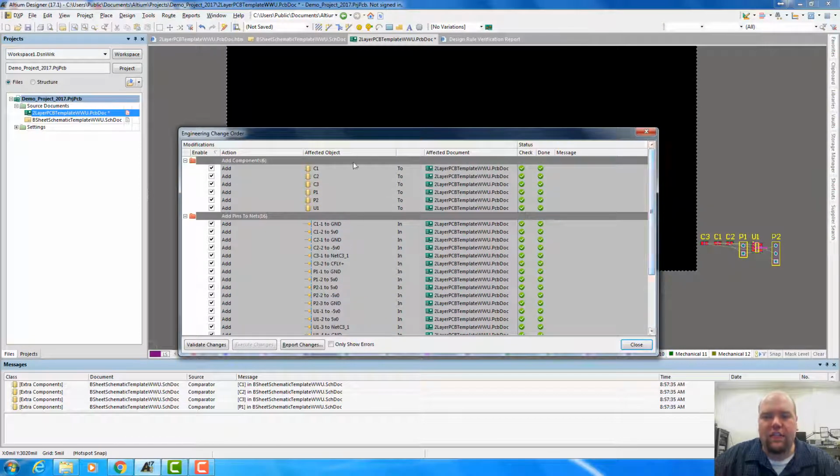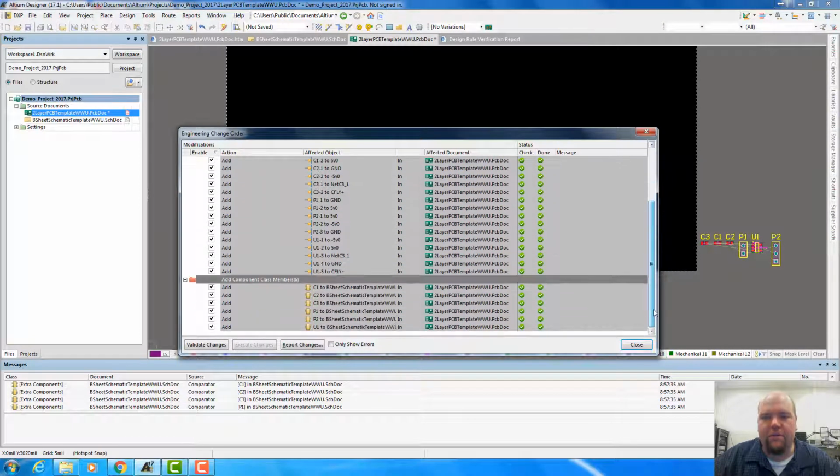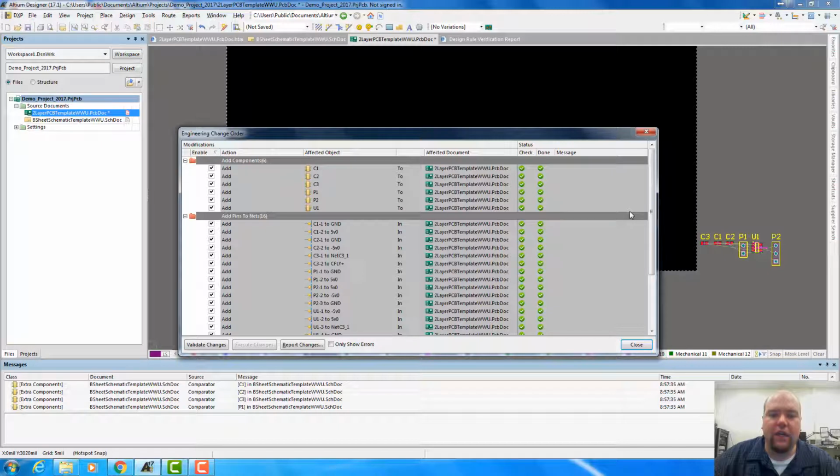Now sometimes you do see something in here that you don't want to change. Sometimes there's a modification that the software notices, but you actually don't want that to happen. For instance, let's say you had a USB connector that used slot cuts for the solder through holes. But you're using a fab that can't do slot cuts, so you change those slot cuts to round, drilled holes. Well, after you do that, the software is going to say there's a difference between what's on the board and what's specified in the schematic, and it will automatically want to remove the part and replace it with the original design.